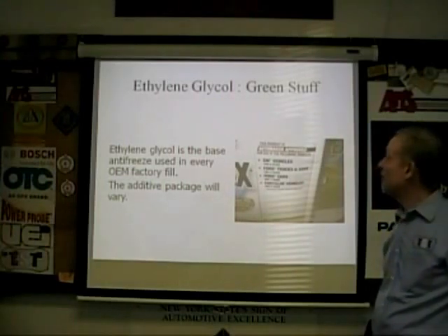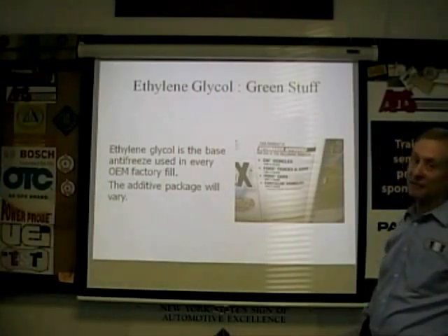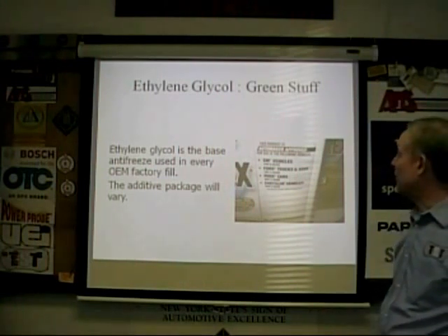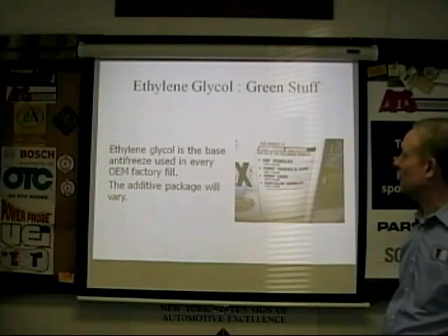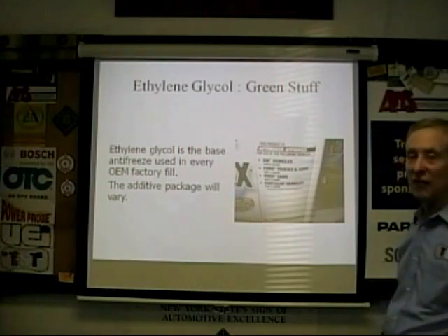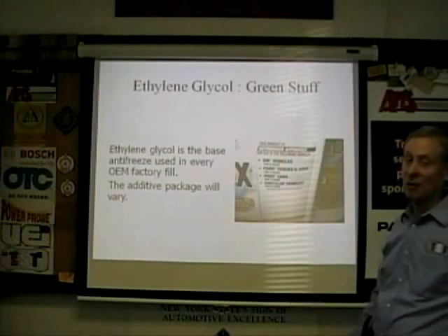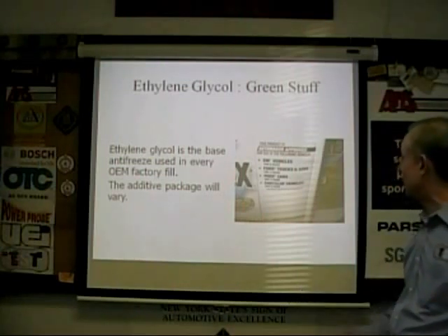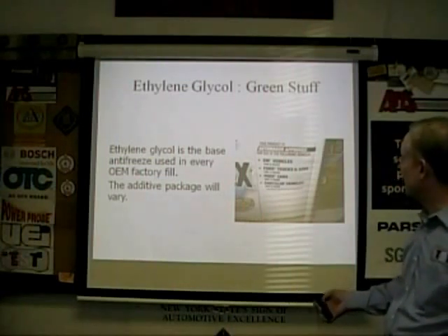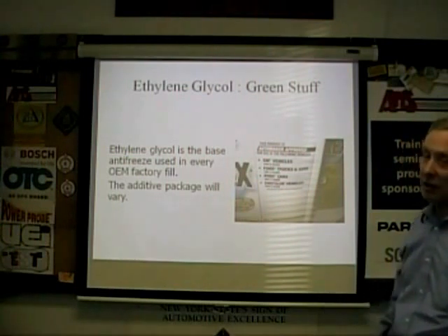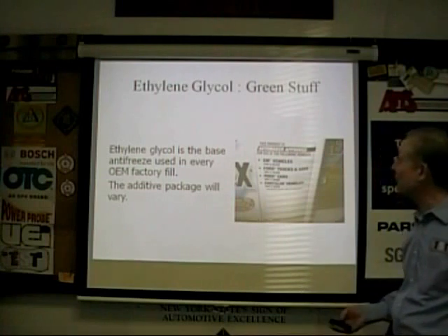Ethylene glycol, green stuff. Ethylene glycol, by the way, is colorless. Green stuff, they just add dyes to it. That's the base. It's used in every factory fill. The additive package varies, and actually that's what this is all about, how it varies and why it's important to you. You can see on this can here, GM, Ford, Chrysler. Nothing here about European, Japanese, or whatever.